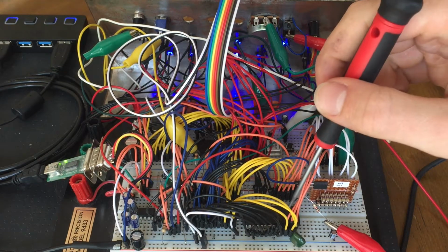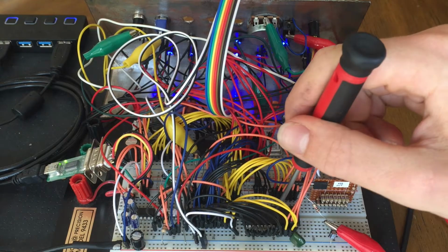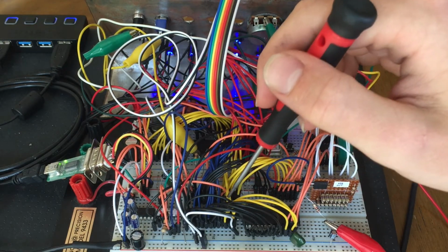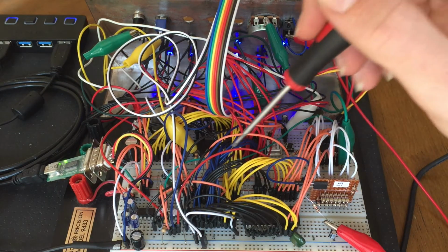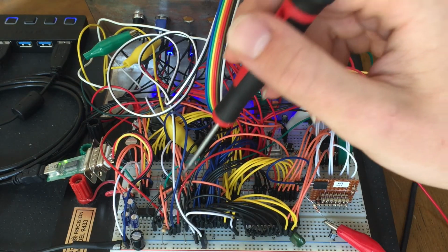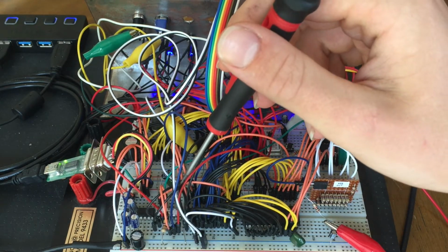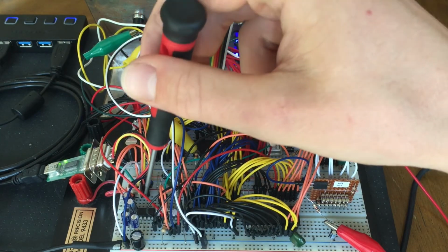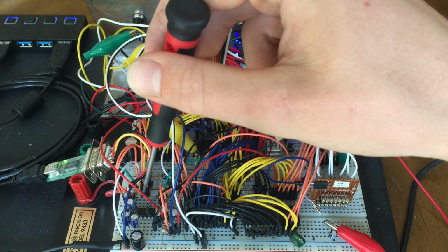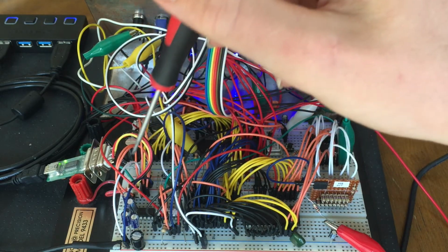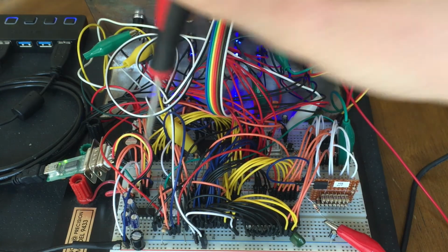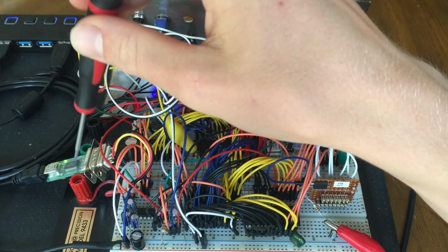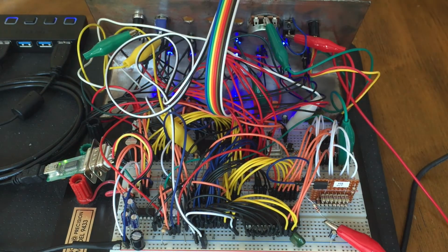The operating system is stored in an 8K EEPROM, and for scratch RAM there's an 8K static RAM. All of the chips are decoded using a 74HC138 decoding chip, and the RS-232 interface is provided by the MAX232 chip that will interface between the logic levels of this and the RS-232 levels needed for my USB to 232 adapter.